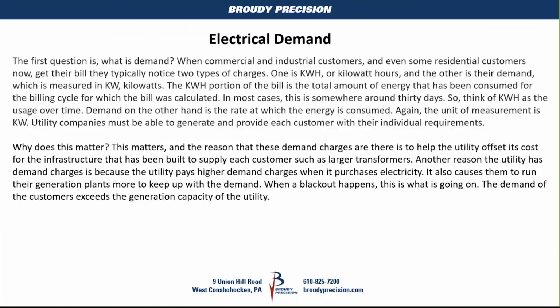If we have a 240 volt lighting circuit, we would divide the 1,000 by 240 for the first guy, and he would need 4.17 amps. And the second guy has 100 watts divided by 240 volts, which is 0.417 amps. So you can see that the first guy, in this very, very simple example, with the 10 100-watt light bulbs, is going to need a larger transformer.